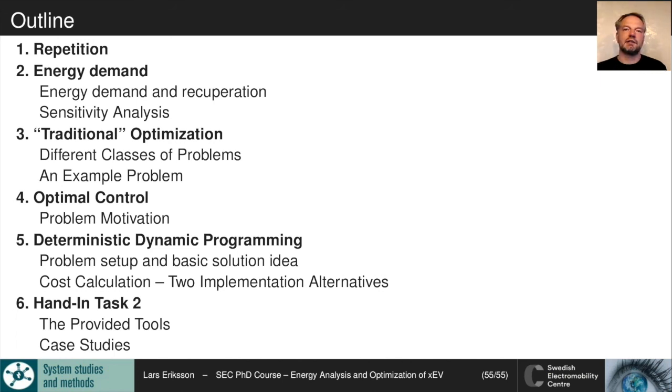With that, I thank you for your attention and give you the reflection that this is offline control. You have to have the full cycle information available, your full trip available, but then you can do the planning optimally. Next lecture will be on real-time control, where we will look at methods of developing real-time controllers that are based on optimal control theory. It will be the equivalent consumption minimization strategy that is a result from minimizing the Hamiltonian and Pontryagin's minimum principle.